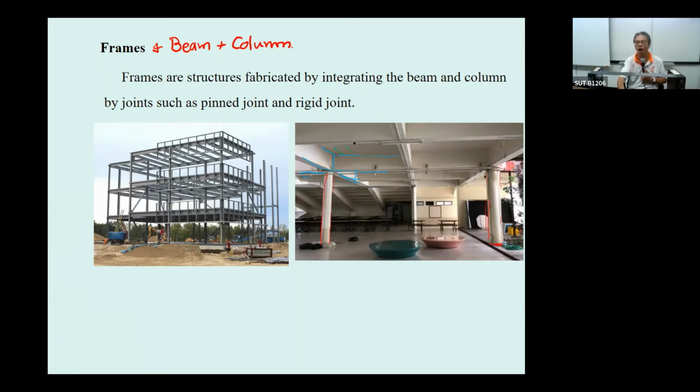Okay, the floor on the beam. The load transfers from the green floor, the green slab, to the light blue beam and to the column. This way, we consider the beam and the column working together. Like I said, after you finish the design of each structural member, you may be required to put them together as a frame to analyze it for taking care of the special loads such as the wind load.